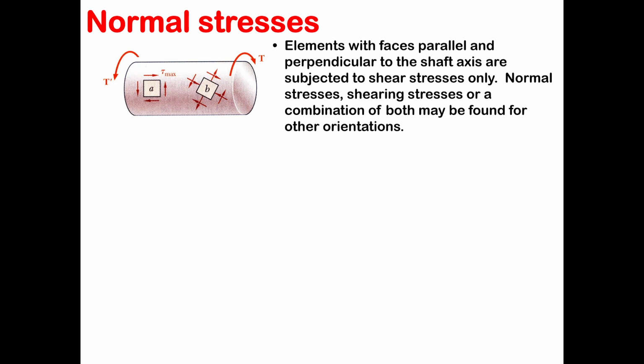If your element has the faces parallel and perpendicular to the shaft axis, then it's only going to be subjected to shear stress, right? But if your element doesn't meet that criteria, meaning that the faces of that element are not perpendicular or parallel to the shaft axis, you are going to have a combination of shear stress and normal stress.